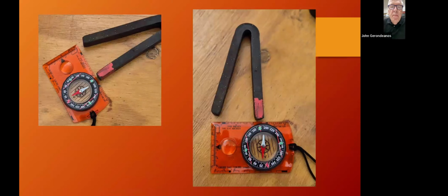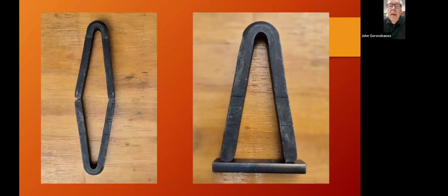As I said, you need a compass, and the compass is to check the polarity of the magnet. Once you've magnetized your magnets, you need to keep them magnetized before you reassemble. One method is to put them pole to pole, so north to south and south to north. The other method is to put something called a keeper across the magnet, which is just a piece of soft iron that completes the magnetic path.